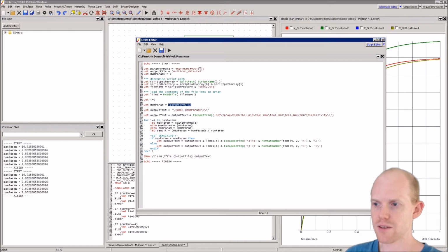And it doesn't matter right now that I doesn't exist here. So if we took away the single quotes, then this would just try and evaluate this curve and store the actual data into this variable. But since we put the single quotes, it's just a formula that can be evaluated later. So then we have the output file name. We're going to save a file called multirundata.txt, and we're going to tell it that we have 3 parameters that we're looking at. That's for our loop.